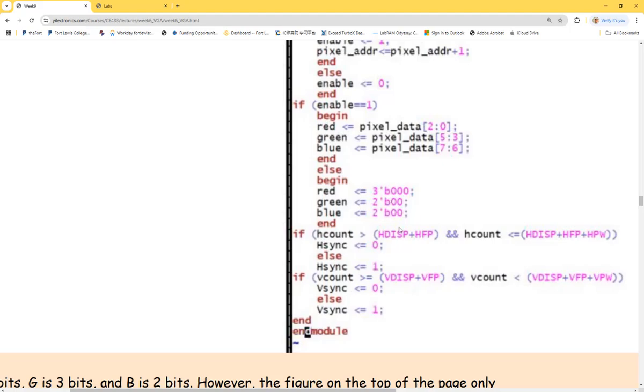And that's the end of it. Nothing else. You can see these ones are just trying to give a sync signal. And that sync signal is being received by the VGA controller within the monitor. So it's going to see the sync signal and start assigning pixels to the next row or column.